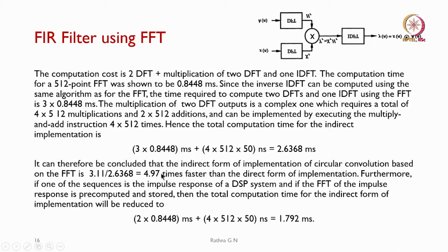So, even using all this complex method, our FFT method is still 4.97 times faster than the direct DFT. And one more thing to keep in mind: because these are predefined coefficients, I will not be recomputing them every time, only our input signal which is coming continuously.